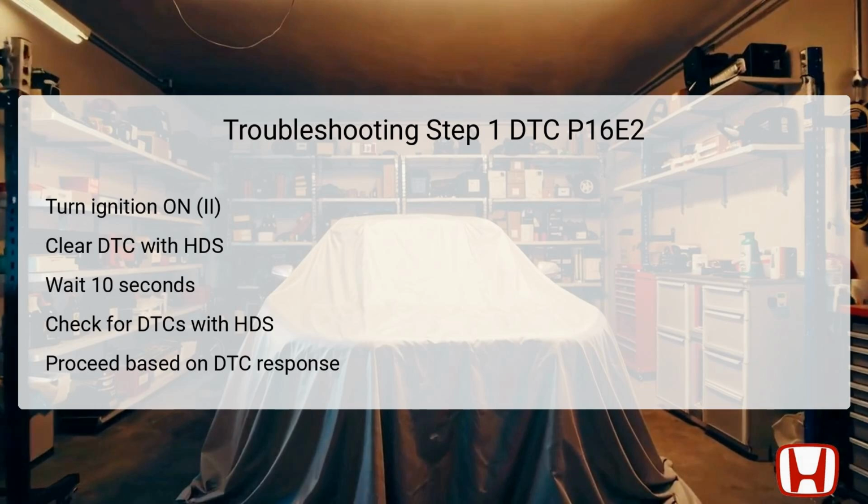Conversely, if the error does not reappear, there may be an intermittent issue, and further investigation into poor connections or loose terminals can be warranted.